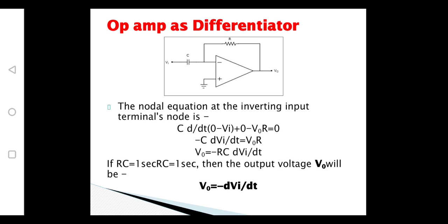If we observe the circuit of this differentiator, the input is given to an inverting amplifier through a capacitance and the output is taken across a resistance. In simple words, a differentiator is nothing but a high pass filter, which allows higher frequency components to pass but rejects lower frequency components.